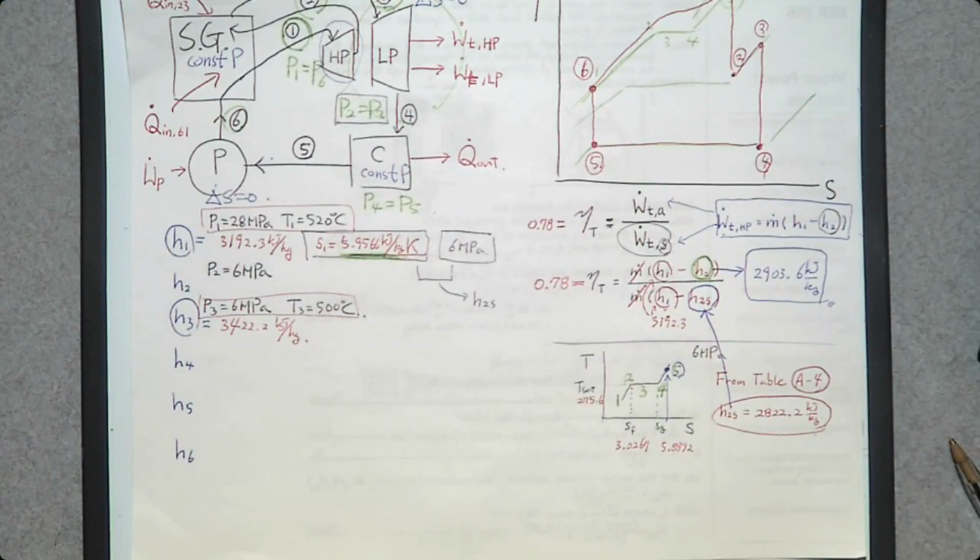So this is a little bit complicated because we have an isentropic turbine efficiency. The only extra step is using this equation. You remember how we determine h2 from the standard ideal Rankine cycle assuming an isentropic process, but we are going to use that process to determine this h2s, and then use this isentropic efficiency equation to determine the actual h2.